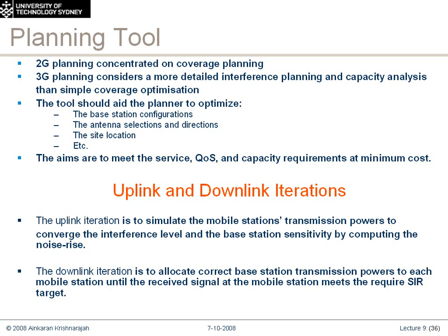So how do we actually get interference? Interference is generally driven by too many base stations cluttered too close to each other, for example. You could also consider it as the soft handover area between 2 base stations being too large. So we have a lot of terminals constantly in soft handover, drawing lots of power from the network. We know soft handover is important in order to have mobility in the CDMA system, but we can't have soft handover areas that are too large either. So there's a balance that we need to maintain.